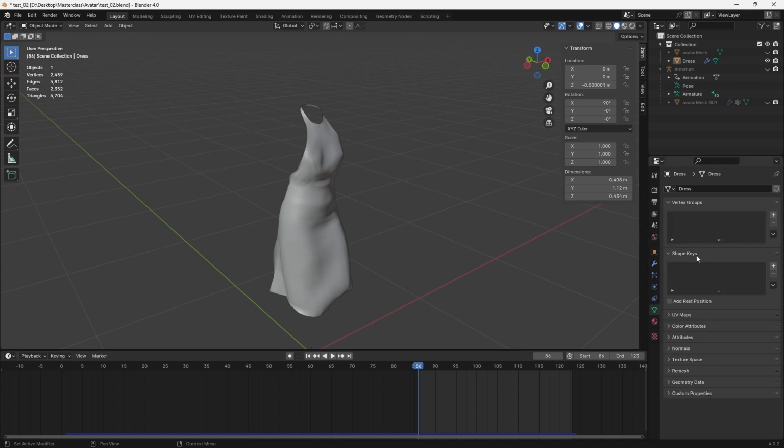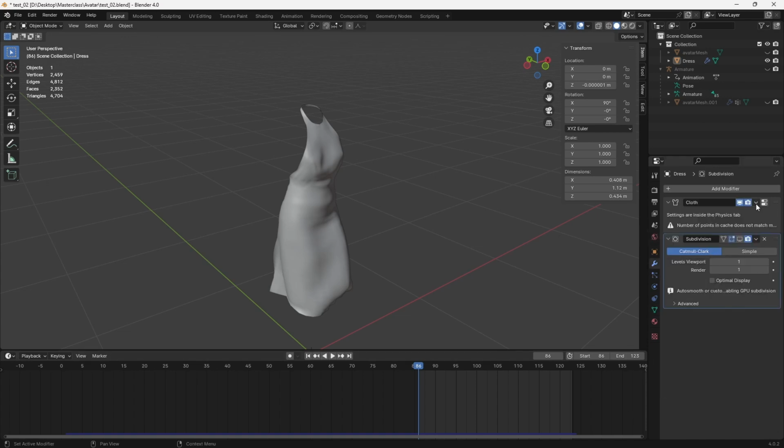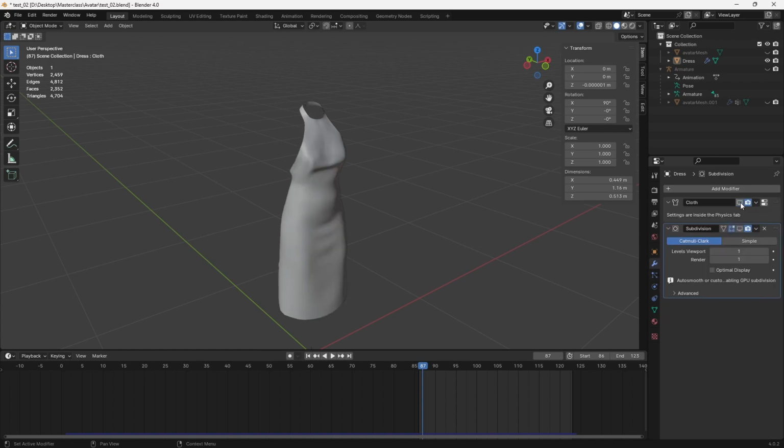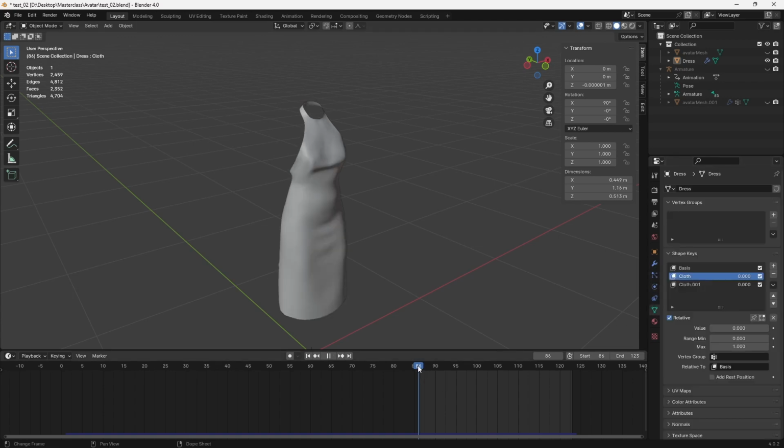To accomplish this, we can leverage shape keys to record the position of vertices for each frame of our animation. This approach can be long and tedious since it involves converting each set of vertices generated by the cloth modifier during the baking process into a shape key, for as many frames as there are in our walk cycle. This results in a collection of vertex positions. We would then need to control their state from the timeline by using keyframes to set their value to 1 if they correspond to the current frame, or 0 if not, and do so for every frame.